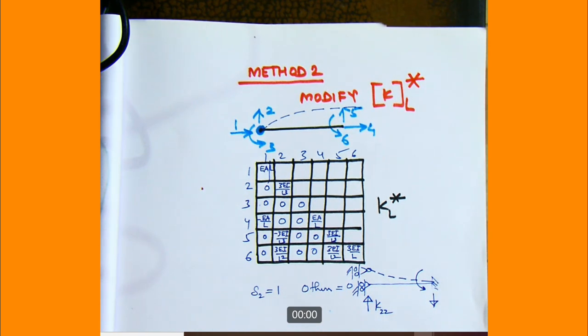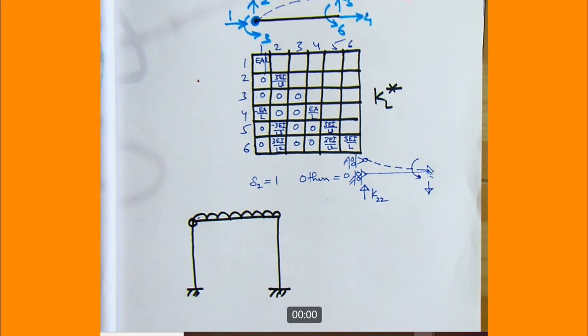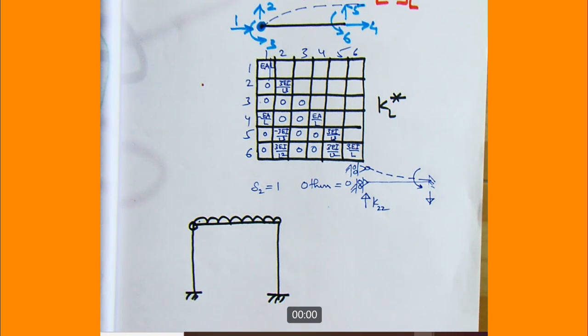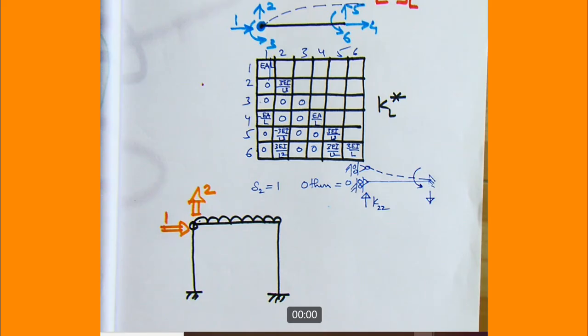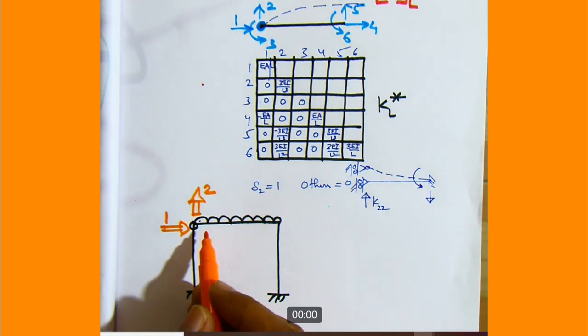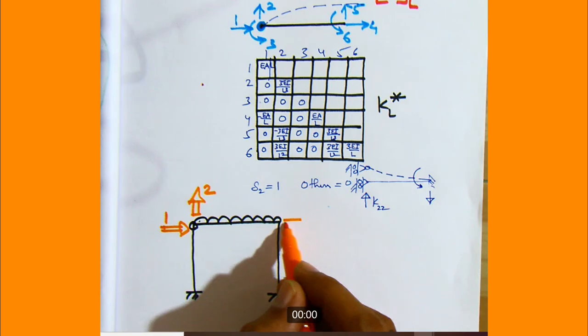So this is our structure, with the loading as before, and now we mark the degrees of freedom. How do we mark the degrees of freedom? This is our degree of freedom number 1. This is our degree of freedom number 2. And where will be 3 now? My question is, where will be 3? Just you can guess. Other joint. No, 3 here now. We have to skip the rotation here. We have to altogether skip the rotation here, and 3 will be here now. And then there are other joint. Yes, correct. And there are 3, then 4, 5.